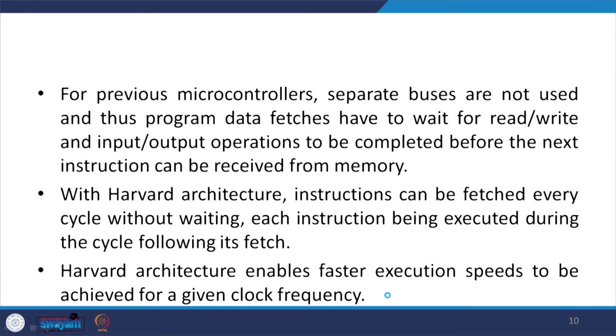So, for previous microcontrollers, separate buses are not used, and thus program data fetches have to wait for read, write and input output operations to be completed before the next instruction can be received from the memory. And with Harvard architecture, instructions can be fetched every cycle without waiting, each instruction being executed during the cycle following its fetch. Okay. Harvard architecture enables faster execution speed to be achieved for a given clock frequency.